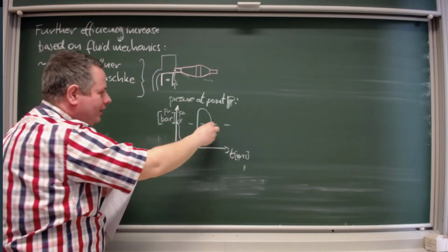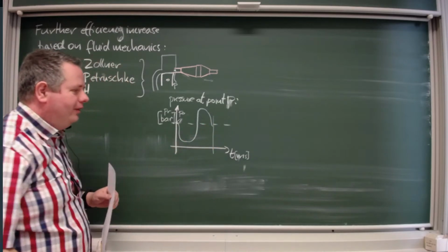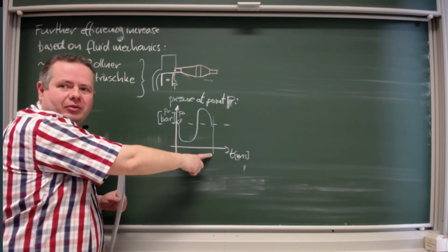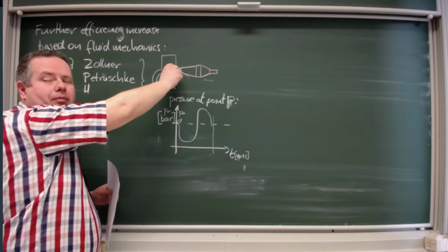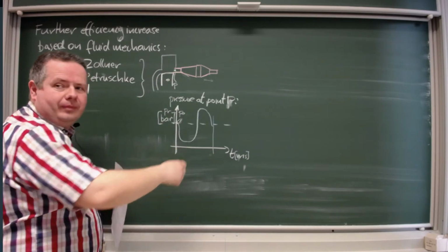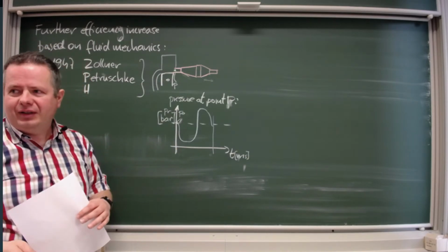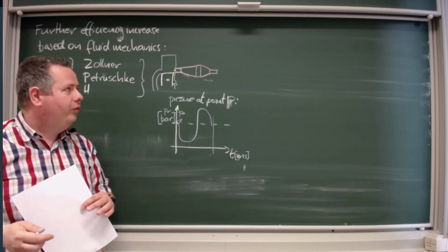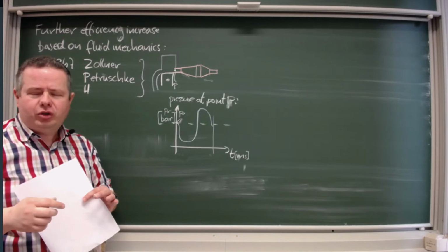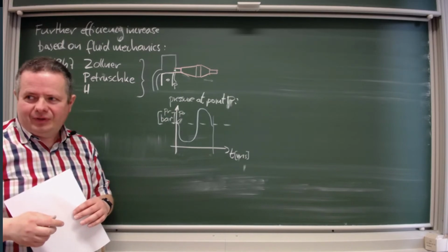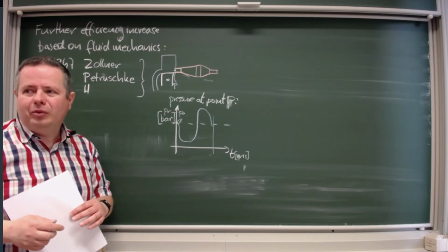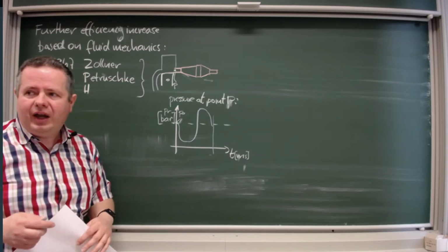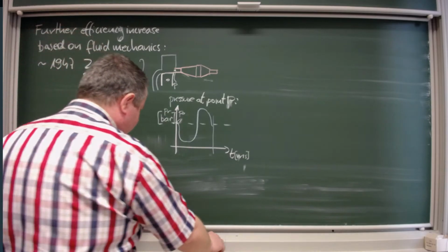And if you can get the right RPM zone that allows the opening of the port for a given time interval, then you get a huge quantity of air mixture in the cylinder. So you get a considerable increase of your power. And this curve is guided by the following quantities.